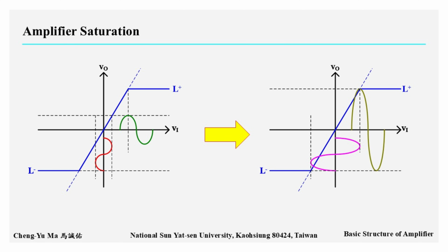When the amplitude of the input signal increases to the purple curve, the maximum amplitude of the input voltage reaches L+/Av and L-/Av. Then, the output voltage, shown as the brown curve, just reaches the saturation output voltages, L+ and L-.